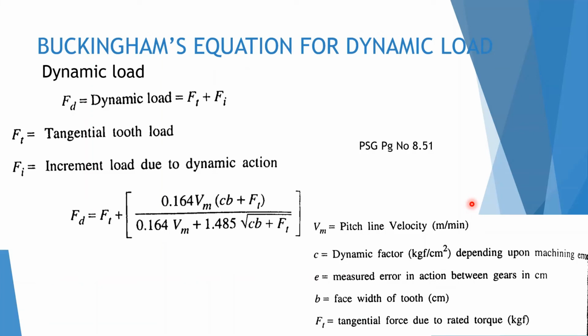So next one, the dynamic load calculated by using Buckingham's equation. This one is very important. By this equation, the dynamic load Fd is equal to Ft plus Fi, where Fi is the incremental load due to dynamic action, and Ft is the tangential tooth load. So there is an incremental load